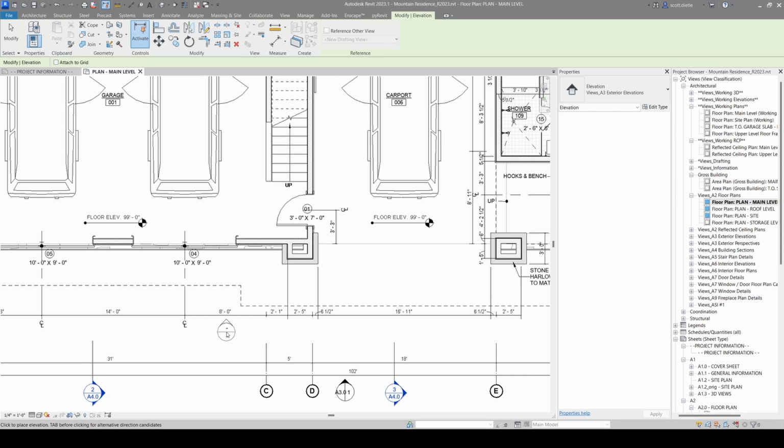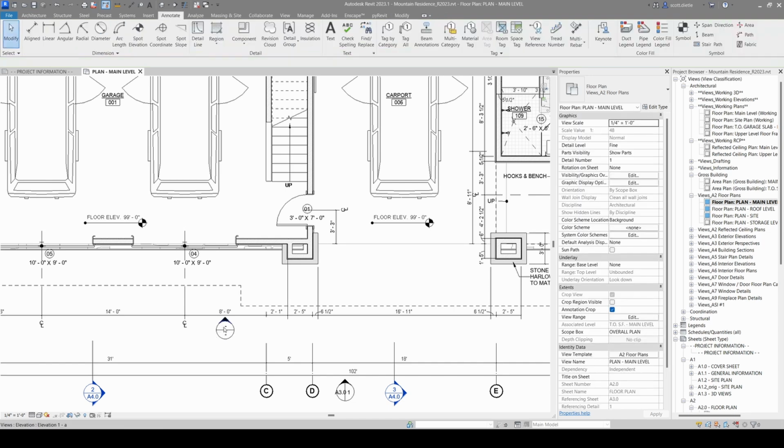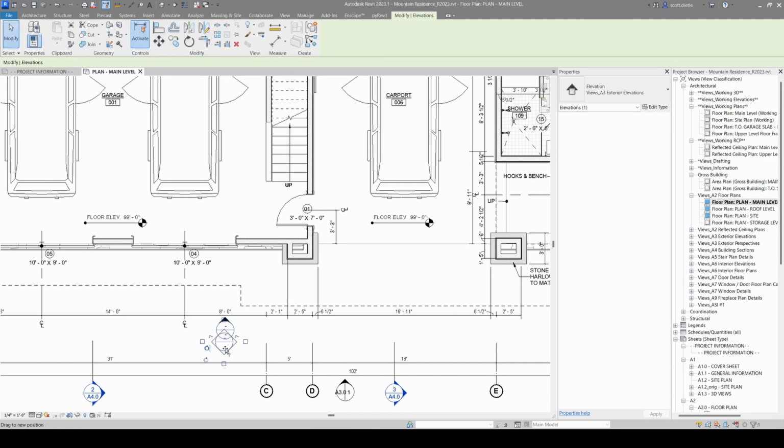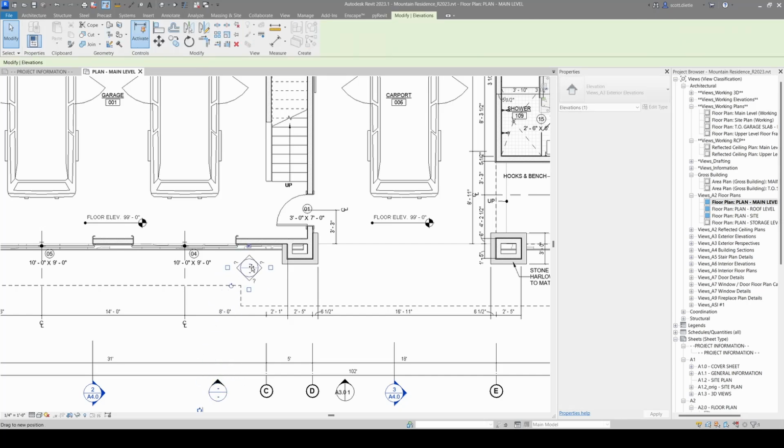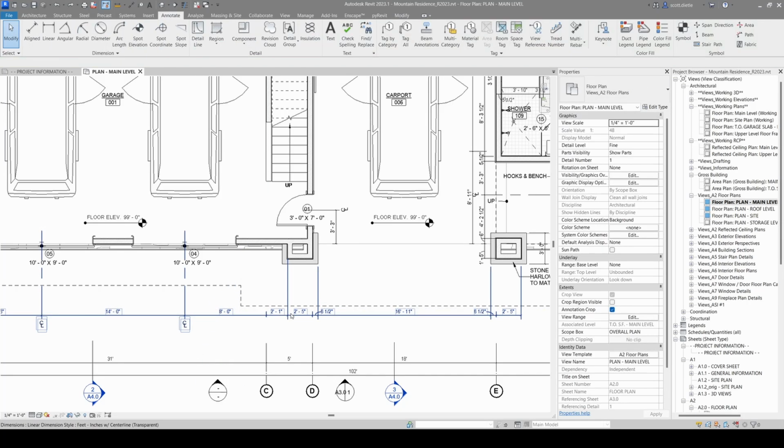So I'm going to move the cursor so that it gets near that east wall and creates an arrowhead. I'm going to click, I'm going to hit escape, and then I'm going to back that head up so that it aligns with my other annotation callouts. I like to keep all my annotation callouts in a nice line across the bottom. I don't like to take my annotations and move them in close. That doesn't do any good.